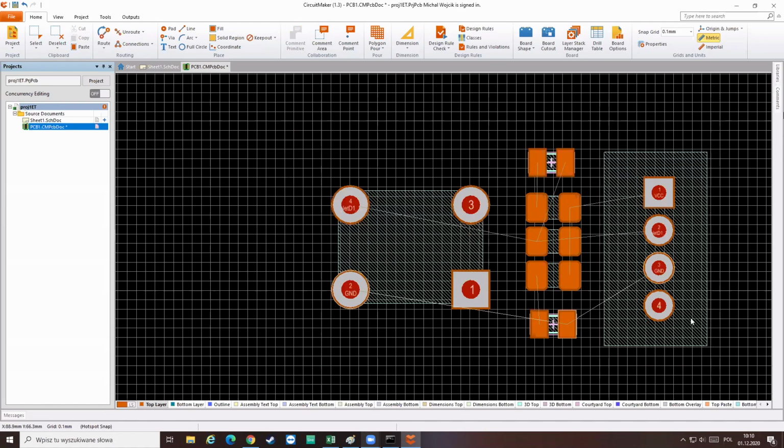All right, let's say I have placed the elements. I don't know if it's perfect right now, but still might be. We'll be using today only two buttons. One will be free, actually. One will be routing, lines, and polygons. We start with routing. So routing actually is connecting now, the suggestion he's giving. So I click routing. Check out, I have the tool on. This cross tells me you got the tool on. If I would like to pull the tool off, I just right click the mouse button. So left mouse button will be for selection, right mouse button for dropping the tools.